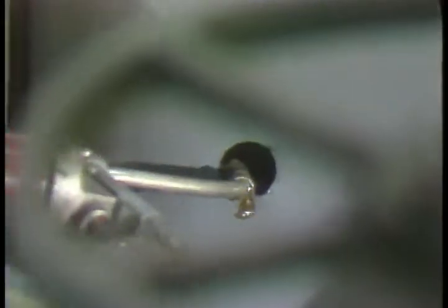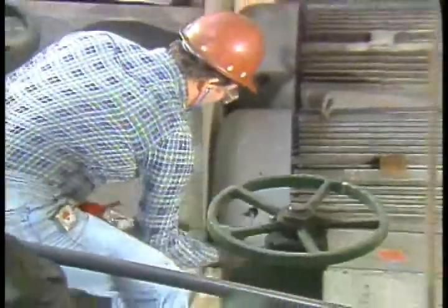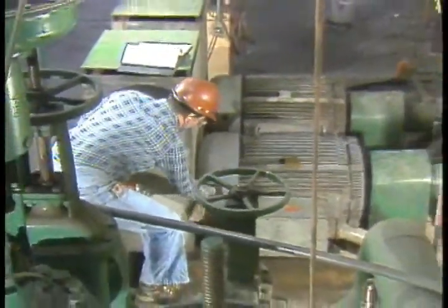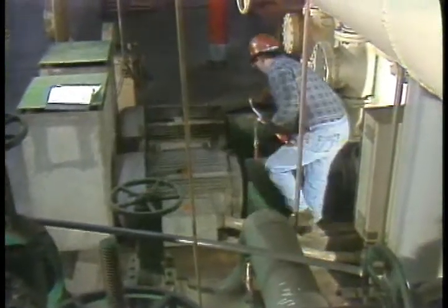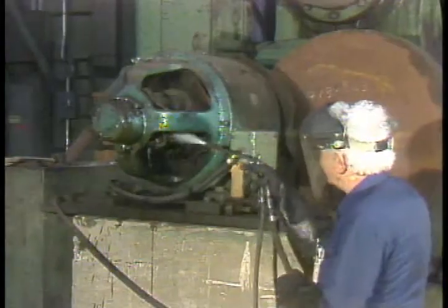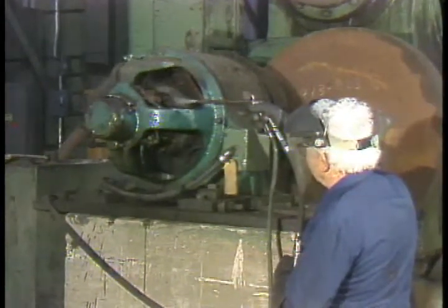In practice, much of motor maintenance involves keeping friction low in motors and associated equipment. High friction increases the load on a motor and makes it more likely to overheat and burn out. Maintenance also should ensure that a motor can get rid of any heat that it does produce.